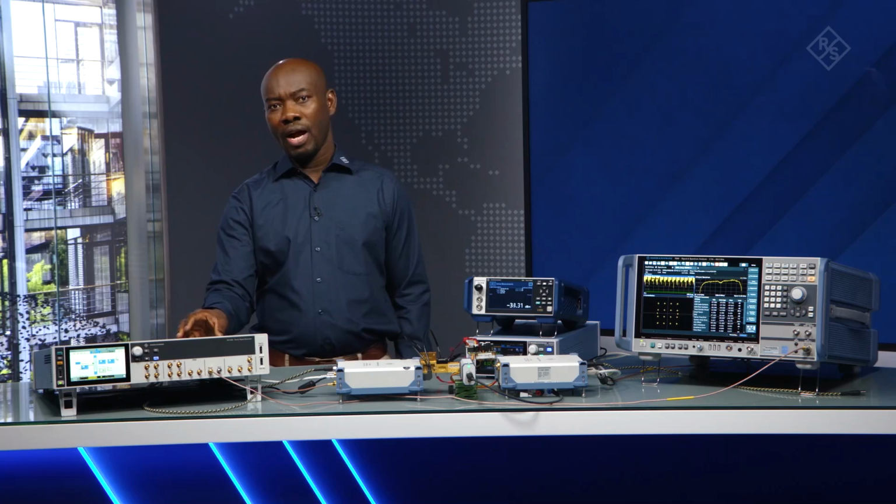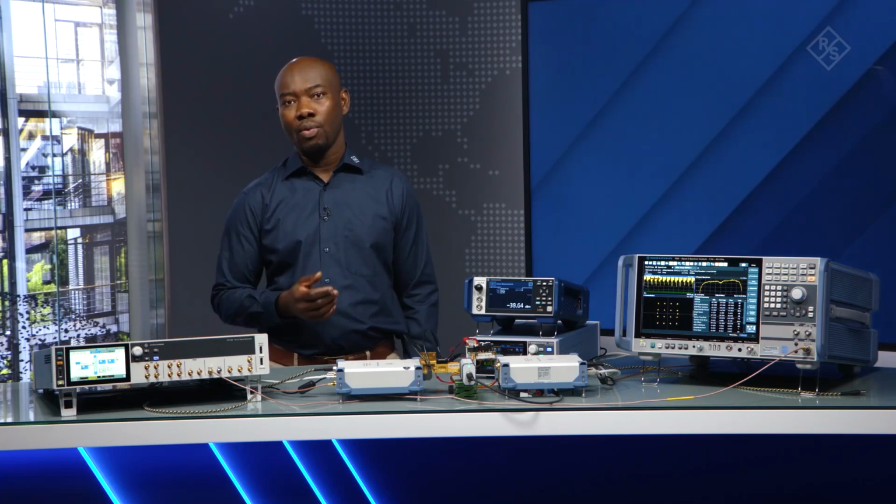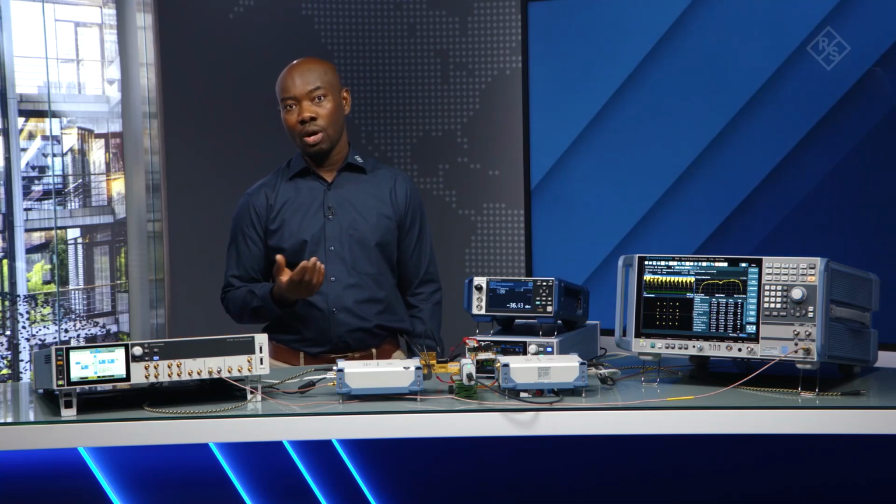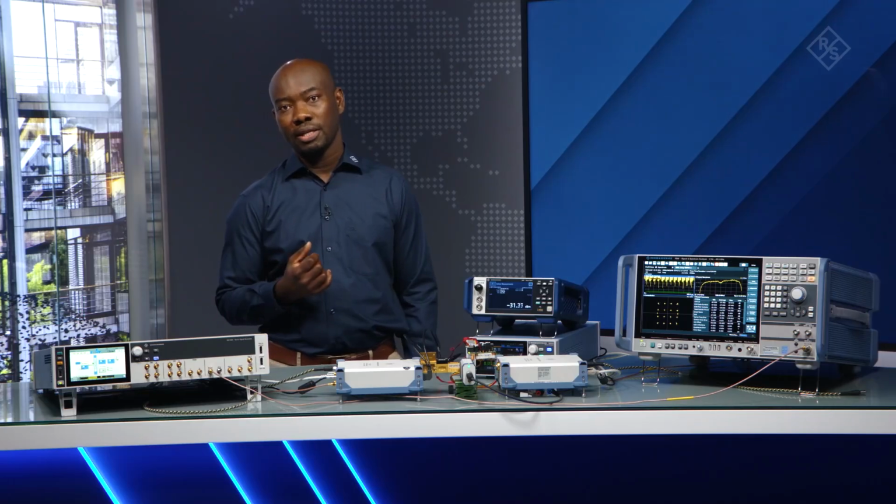In addition to the RF interface, the SFI 100A also has analog IQ outputs, ideal for wideband signal generation in the baseband. Let's have a closer look at the solution with the help of two experiments: direct IF measurements at 14 GHz and characterizing a D-band power amplifier module at 144 GHz.